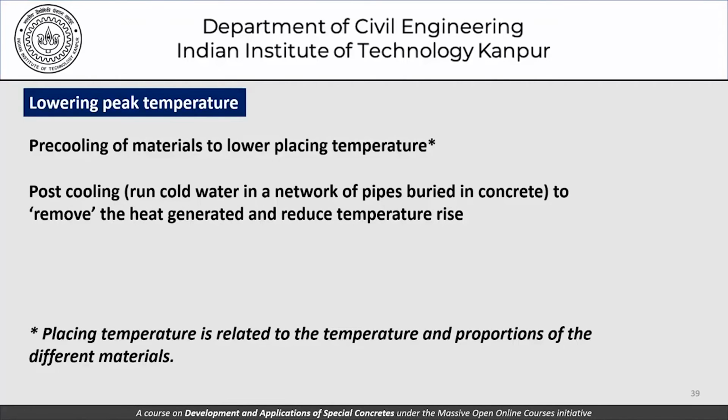This method helps us remove the heat from the core directly by running cold water through this network of pipes, which takes away the heat from the core directly. So we do not have to wait for that heat to be dissipated only from the surface of concrete. We take it away directly through this water flow.